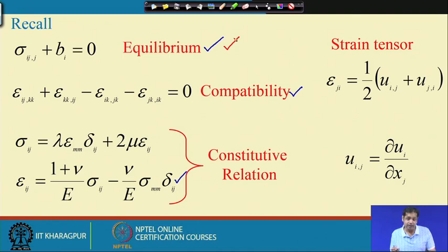Now, when we write the displacement formulation, the equilibrium equation we have to use. Since the equations are written in terms of displacement, we will not use the compatibility relation, because the displacement is completely eliminated. Instead, we use the strain displacement relation. But please note, it is the same set of information, we are not compromising with the information. And in the constitutive relation we will use this other expression. These three equations combine and give us the equation in terms of displacement. Let us do that exercise.